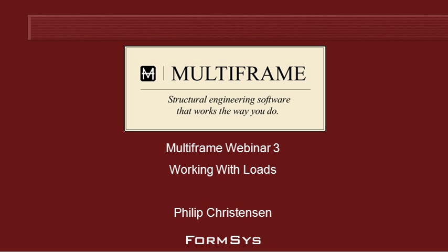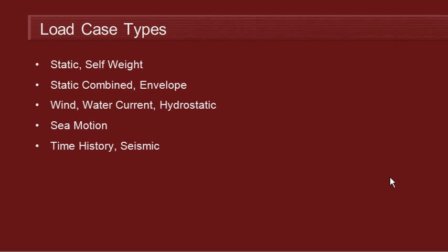We've seen how we can apply different types of loads, and of course to manage our loads we want to group them together into load cases. Multiframe offers a lot of different load case types, so static load cases and self-weight load cases are pretty self-explanatory. We can create load case combinations, and we can also create envelope load cases. Strictly speaking, they're more for managing results rather than application of loads, but they're still a type of case in